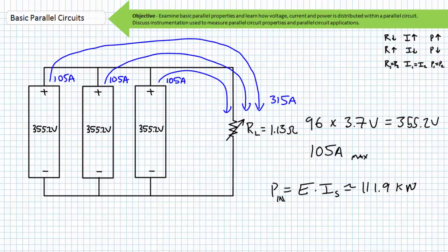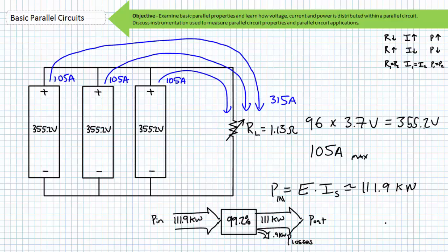The peak output of the original Chevy Volt's electric motor is actually 111 kilowatts, so I've taken obvious liberties with the current capable of being produced by the parallel string to make things simple. I sincerely doubt the inner workings of this vehicle is 99.2% efficient at peak power. We'll return to motors and the maximum power transfer theorem in later lectures. The point is, losses will always occur, and you need to anticipate these losses in system design. This also goes to show that voltage sources identical in magnitude placed in parallel with one another simply provide an increased current range in the case of extreme demand.